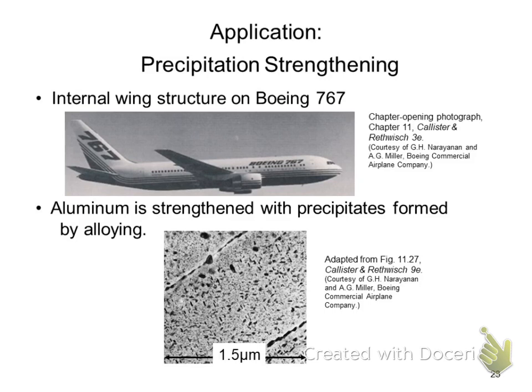Here's an example of this particular precipitation strengthening. This is an airplane wing, and they use this aluminum, but aluminum tends to deform easily. We like that in some ways because it's very light, but the deformation needs to be stiffened up also, and we can use precipitates inside it, using a ceramic usually, or a metal alloy, either way, inside the material. So each of these different little black dots within here are that precipitate, and you can see them.